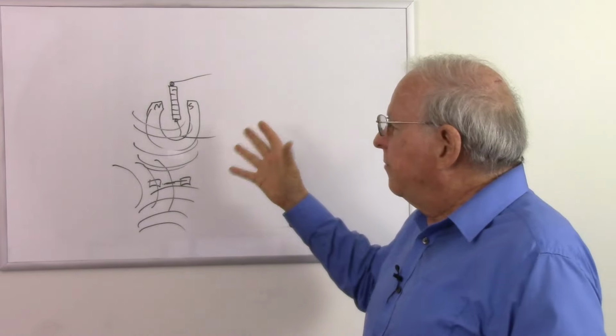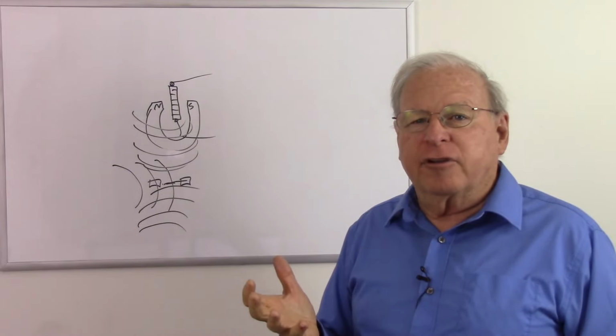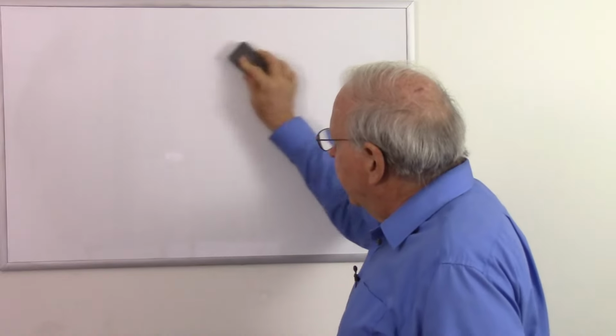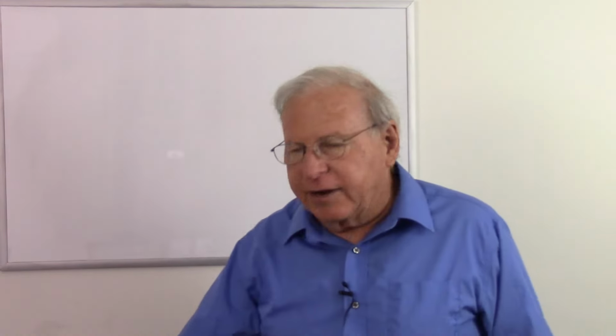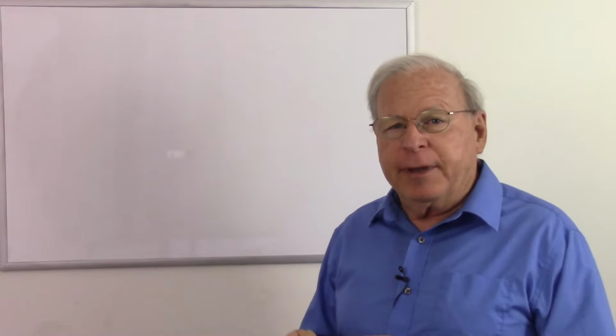So this is not an omnidirectional microphone, but it is a bidirectional microphone. So there are two different types of microphones that have different pickup patterns based simply on the construction of the microphone. So let's take a look at how these pickup patterns are determined and look at what they are and how we can manipulate microphones to have different pickup patterns.